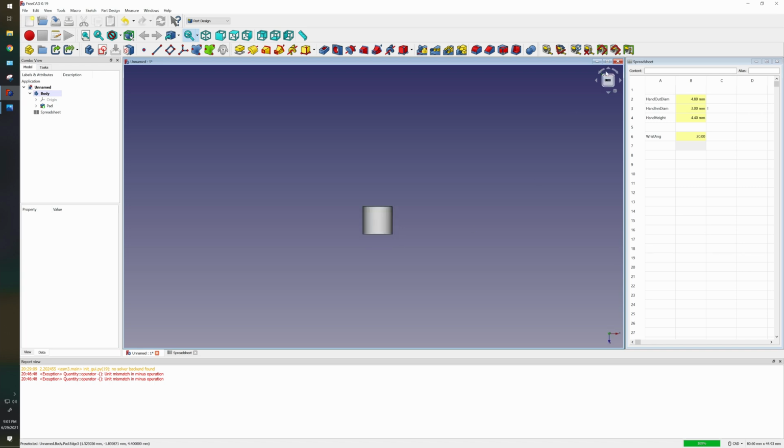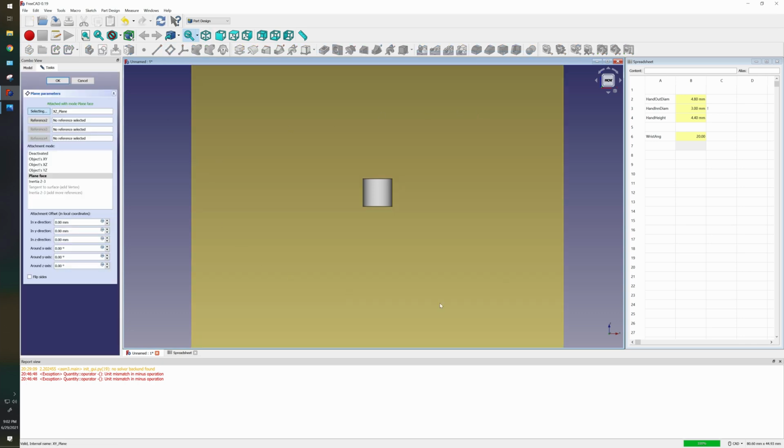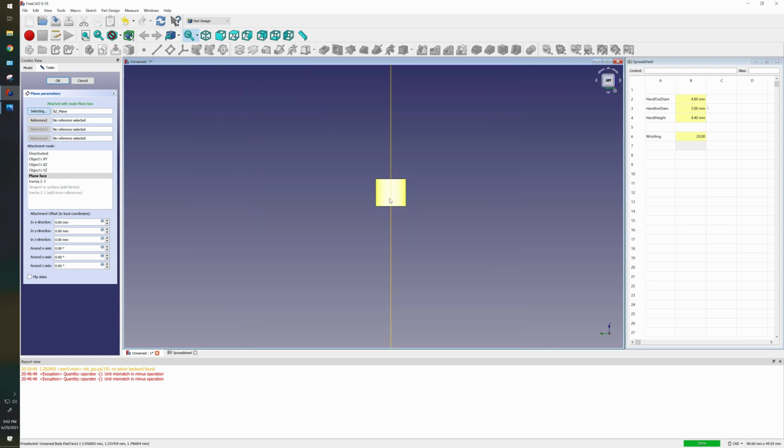And in order to make that angle, let's go back to the front. I am going to need what's called a datum plane. Go to origins, and my front plane right here, ZX. So if I go to my ZX right here, and then tell it to create the datum plane, it will create it right there and already filled in plane face ZX. So let's turn this around a little bit. And what I want to do is create that angle.